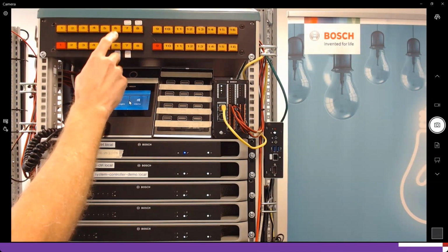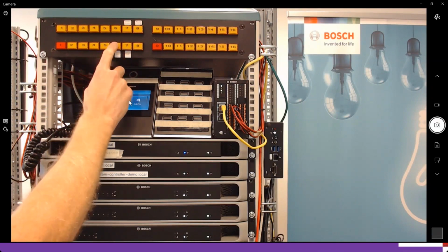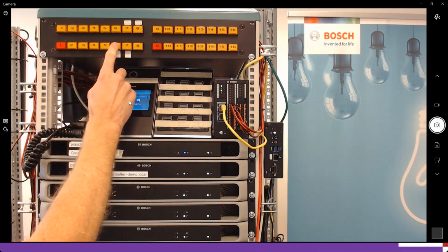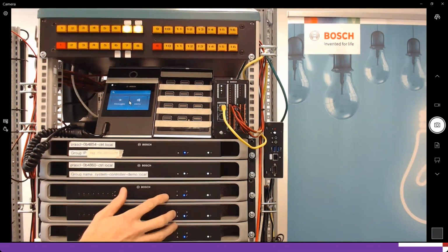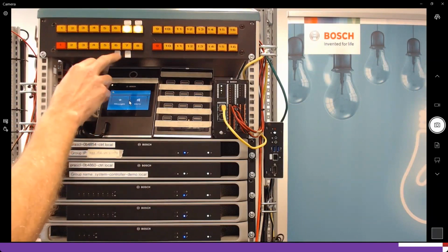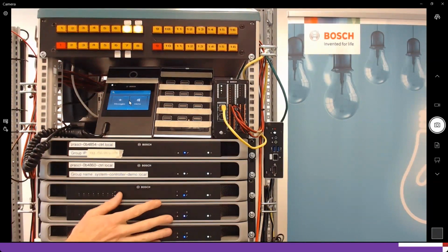This is also a control input which is at the moment connected to the MPS, but you could have a similar function here that you have an external main supply fault. What you see now is, for example, that you have the amplifiers here giving a blue LED. That means that the system gets into a snooze mode. So the power is now reduced, because there's an external mains fault, for example, if a UPS is now active, so it's immediately in the snooze mode.